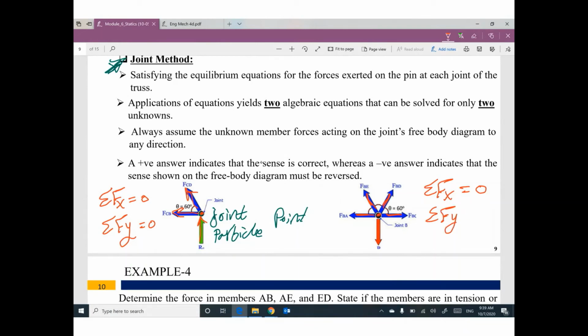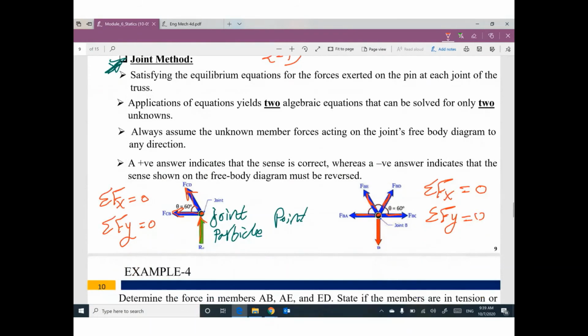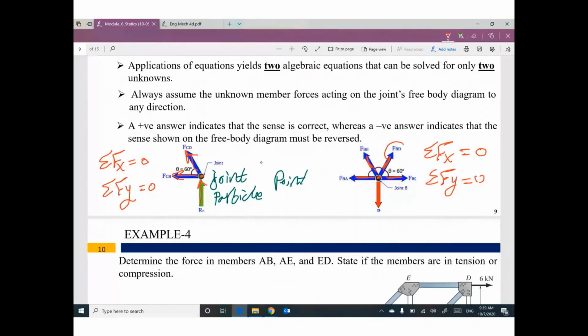Guys, we are talking about truss in 2D, 2 dimension. We will not talk about anything in 3D more in this course. We are done. So everything in 2D. So you need to figure out what is the x and y component for this one, what is the x and y component for this one, and so on. Finally, summation of all x components equals 0, summation of all y components equals 0. Once you are done, I can figure out how much these forces are.